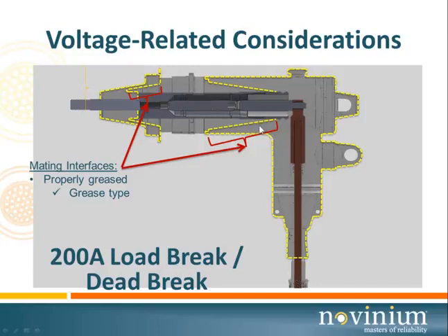Silicone grease does not migrate into the insulation. It's a misconception. People think of the interface drying out, that because the grease got absorbed in. It does not absorb in. Got to use the proper grease. The heavier grease stays in place.